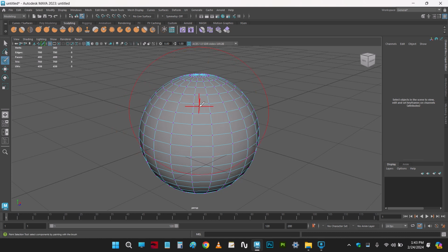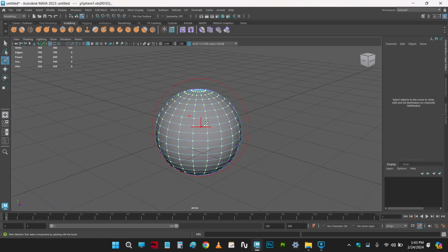So paint selection is also kind of a painting thing. So we are getting a kind of circle over here. This is known as the brush. Right click vertex, so we are painting it, we are selecting it, but the thing is that the brush is very big. So for decreasing or increasing the size of this brush, simply press B and then middle mouse to the right side, to the left side. When increasing or decreasing the radius of the brush, pressing B to the right side, to the left side. So this way. So if I get into the faces, we can see.